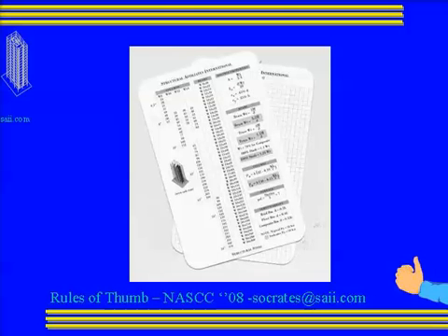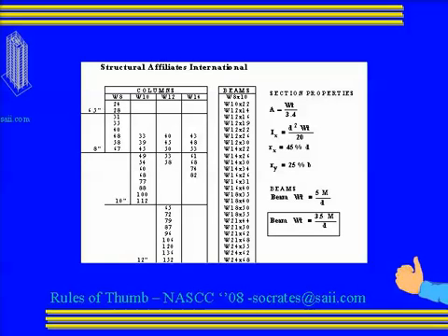First of all, in the center you have your economy section beams, in case you don't remember them, and a few more. And then on the very left you have the columns grouped by flange width, so that you can use that RY that we talked about. And then you have the equations that we're describing here. Anytime you see a shaded equation, and I'll show it boxed in here, that means it's for Fy equals 50. Okay? So it's very simple.